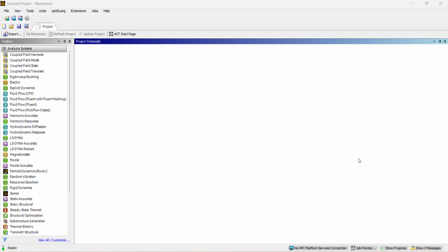So in this case, we are analyzing a cantilever beam. Some examples of cantilever beams might be a diving board or maybe a balcony on an apartment. And so we can use static structural in ANSYS as a simulation tool to predict how these different structures will behave in the real world before we actually start to build it, which helps us to save time and money that might have gone into building a real world structure.